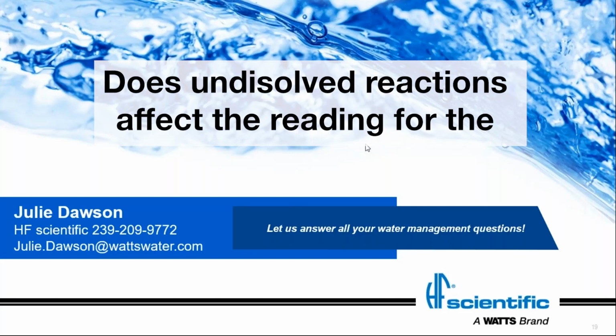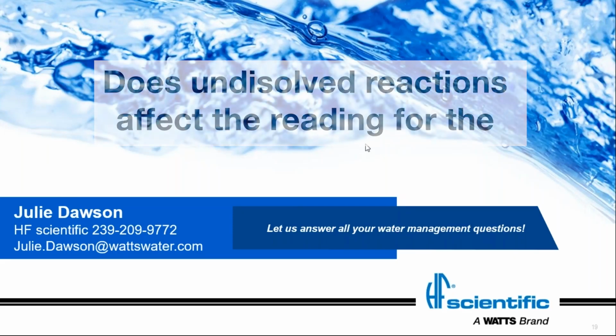So if you get a foil packet that says it's appropriate to measure a 10 milliliter sample up to 4 ppm, there's probably enough DPD in there to measure up to 6 ppm. So it depends on how much is undissolved. If it's falling out and the whole clump is at the bottom and none of it's dissolving, certainly I'm concerned with that. But if I see a grain or two of DPD or of salt left at the bottom, I'm not as concerned with that because it is bucket chemistry.